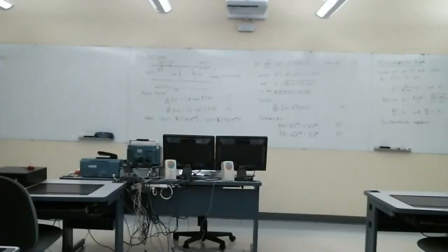So going back to our expressions for our phasors. I'm going to call the wave that's propagating down in the positive z direction phasor V plus. It includes this e to the minus gamma z term. And similarly, we'll call the other one V minus. I know there's a lot of notation you have to absorb here.